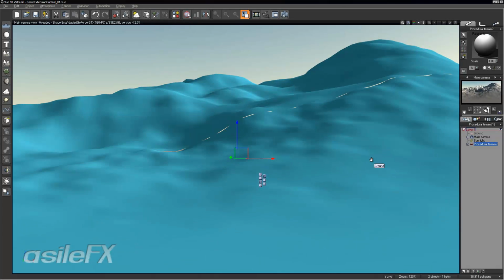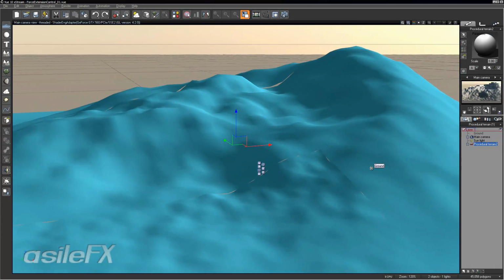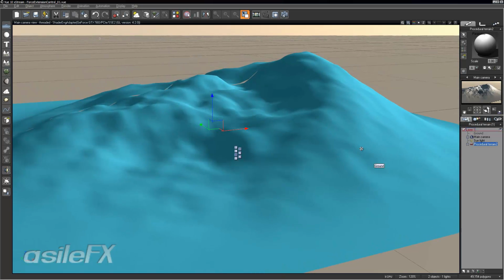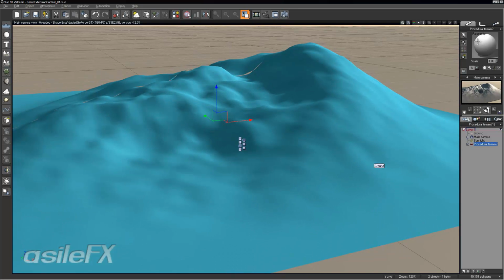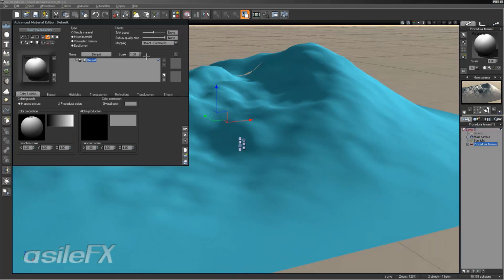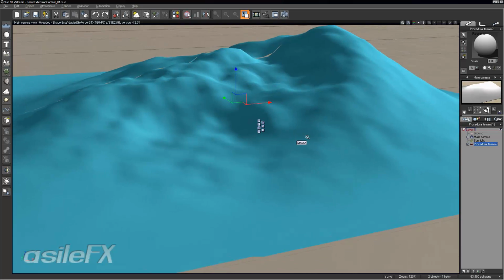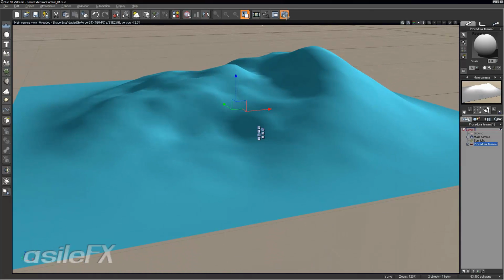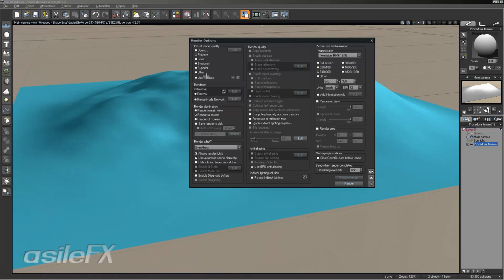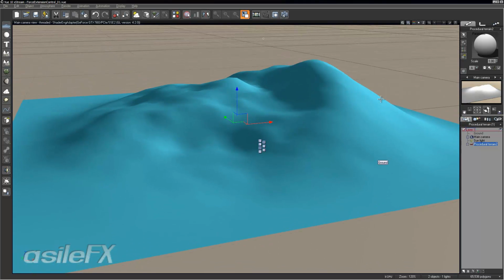Now this is actually going to be incorrect for the moment, because there is one little thing about terrains that has an issue with this input node. First we'll take a look at a render, and one thing we can do to really look at the color being produced is, in the material editor, ignore the atmosphere and ignore lighting, which will show us just the color output. So no diffusion, no shadows or anything. I'm just going to render to screen really quick. We can take a look at this, and then we'll fix the altitude output so that it works correctly within the function.